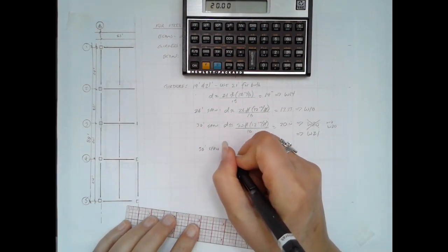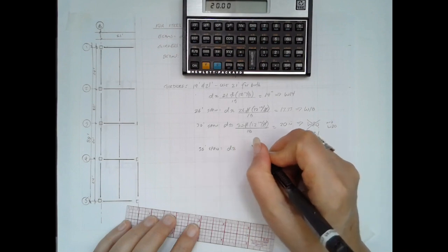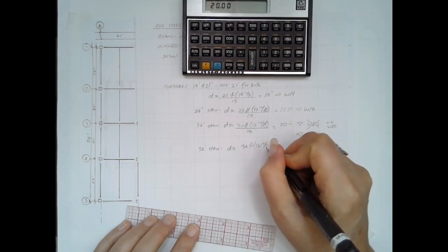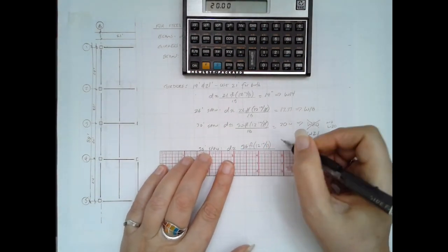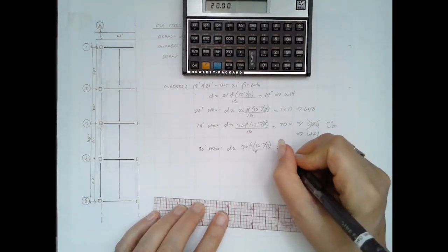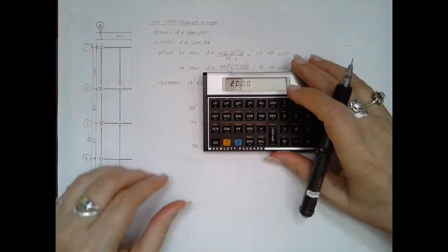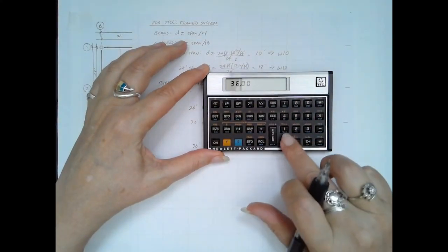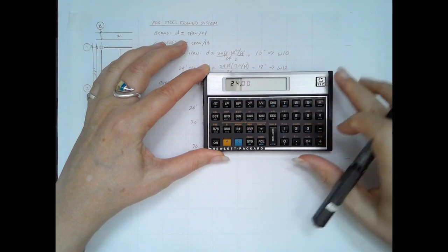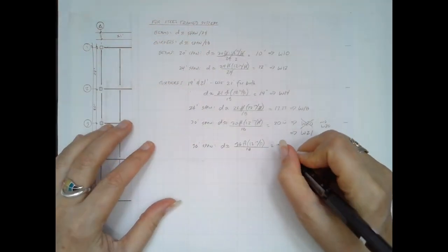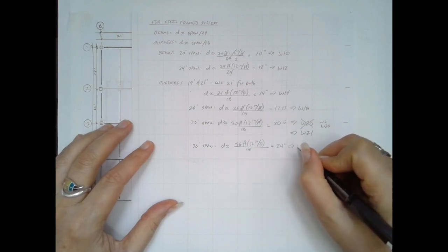And then the last one, I marked that as a 36-foot span accidentally. That's actually 34. Correct that later on. It actually rounds up to about the same. So for that 36-foot span that I chose, that comes out to an even 24. So we pick a W24 there.